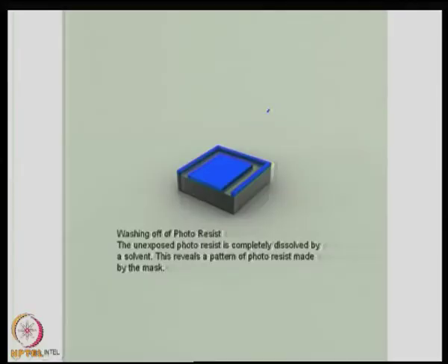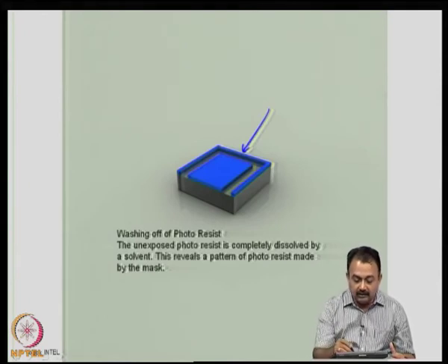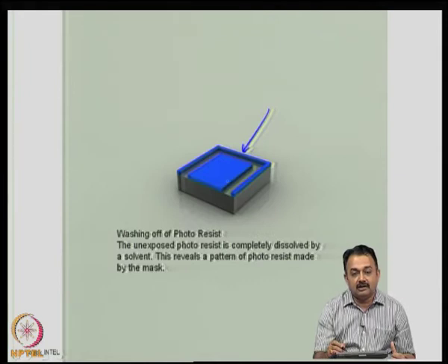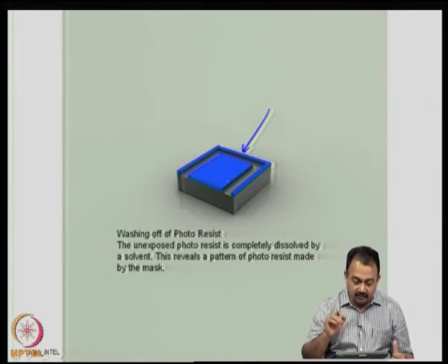Now, once the photoresist is applied and you have exposed and also you have developed, okay, you are now seeing the image of one of the layers. As you can see, the blue layer is present, that represents those areas of the photoresist that need to remain there, protecting certain areas of the base material or the silicon here, or the silicon dioxide as the case may be.